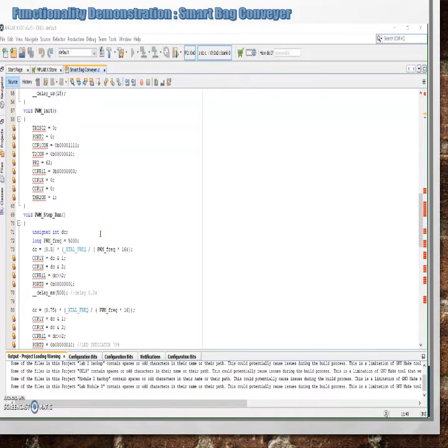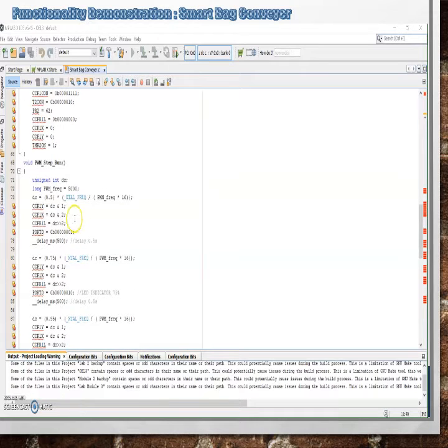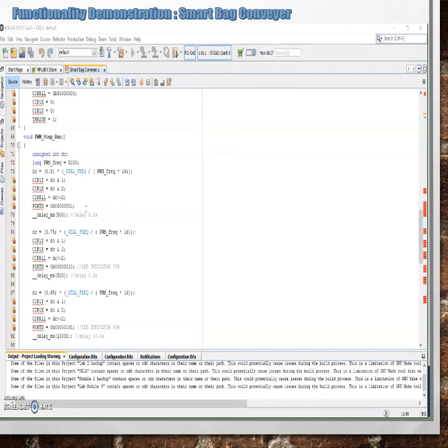The next is our conveyor running. The first one is set at DC 0.5, that is 50% of motor running. Then for each step it will delay for 0.5 second, that means our motor will not have a sudden change of speed while running.